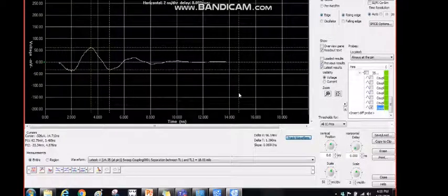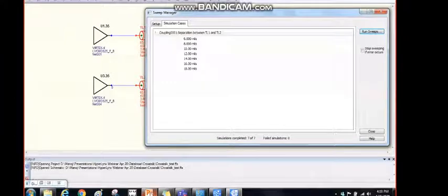That means we cannot have a clearance between components of the order of 18 mil, which is something very huge. So people tend to take extra care, when we are talking specifically of high speed traces, so it is not applicable to all the signals. It is something where the edge rates are very high. So for those signals, I would be placing a shield, maybe a ground shield, something of this sort.